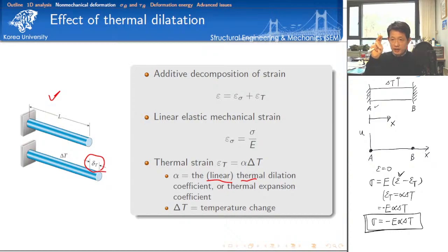And if humidity increases, then the volume increases. Okay, let's consider the casting of concrete to a form. Usually, when you pour the concrete it is completely wet, isn't it? And then during the hydration reaction, the pore space of concrete would lose the moisture. The water. The moisture drops. The humidity drops.